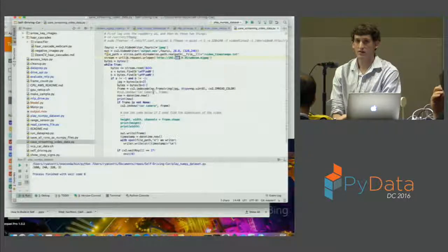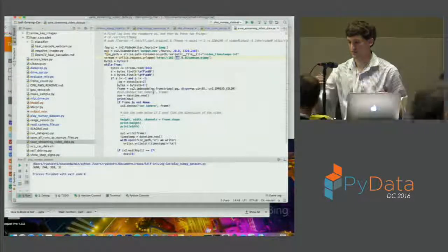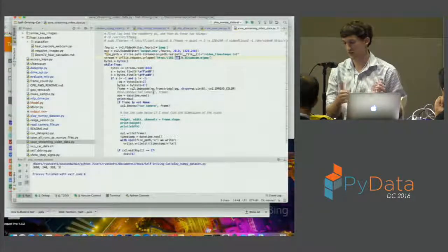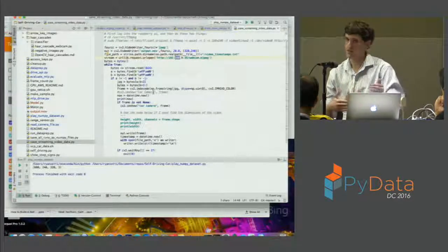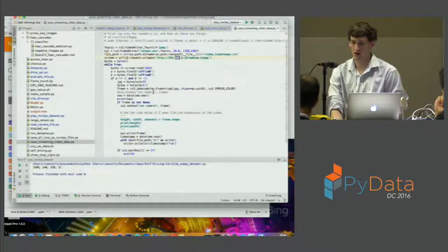Would you be throwing away any image in which the car just paused? No, so that's something I maybe should have changed. My car does kind of overcorrect sometimes, and that's probably because the car is actually coasting sometimes, but when I pass in the data to the model, I never actually tell it that it's coasting. I say that this command was always on this entire time. So in hindsight, that might be why it's overcorrecting, because it should coast more than I'm telling it it's coasting.